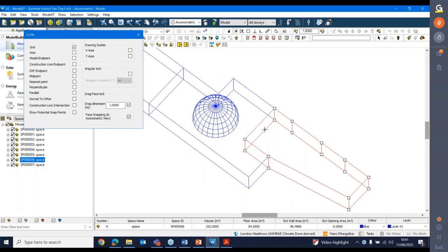So I could put a hole in that surface there, which I'll do later on, the same size as that surface. If I put a big hole in that surface, that has the same effect as deleting that surface, but the surface is still there, and you've got a massive hole in it. If you have a hole between zones, as long as you're using our macroflow tool, you'll get buoyancy driven airflow through that hole, because the rooms are at different temperatures. If you're using our lighting tool, you'll get light transmittance through that hole. If you're using our shading tool, you will get solar tracking through that hole.